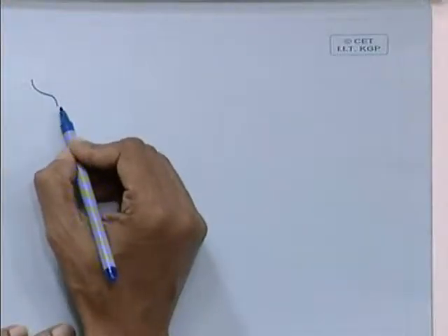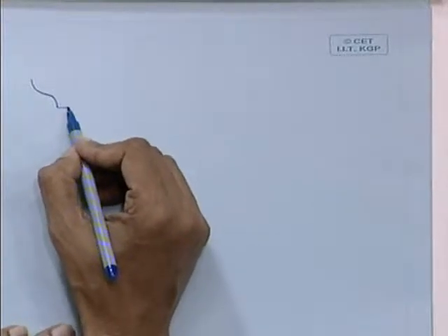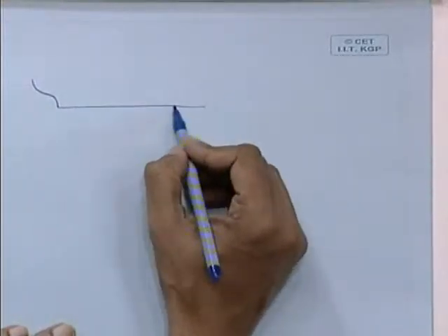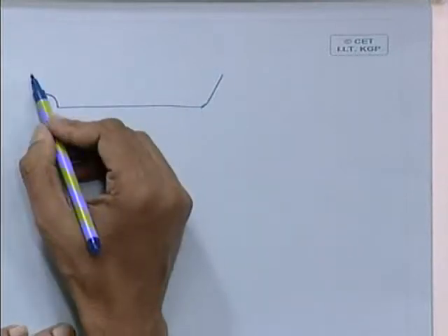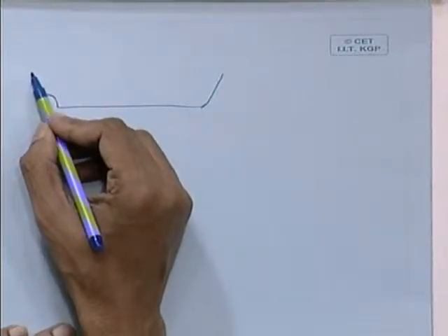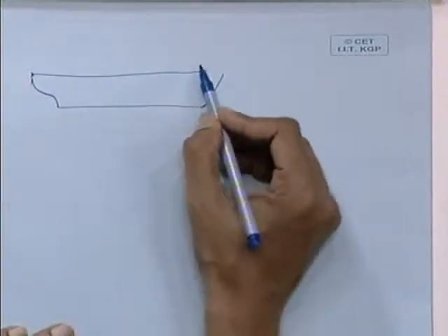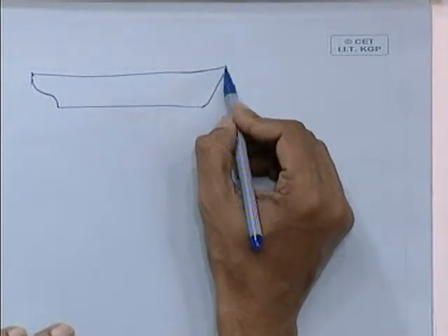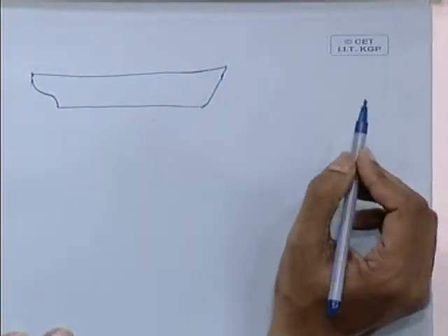Of course, the camber you cannot show in the curve, but the shear, since you are drawing the deckhead side, should be clearly indicated in the profile view. In the profile view you will have this shear curve. So, this we incorporated in the lines drawing.